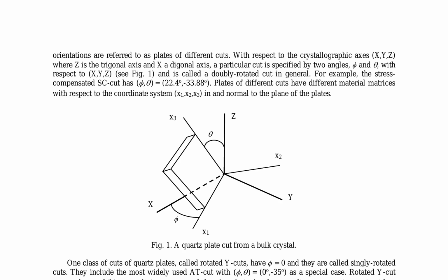The paper highlights the importance of considering anisotropy and piezoelectric coupling in the analysis of quartz resonators. This is because these factors significantly influence the vibration and wave propagation characteristics of the plates. By employing approximate two-dimensional theories derived from the three-dimensional equations, researchers can model vibrations of piezoelectric plates and apply them to the analysis and design of quartz resonators.